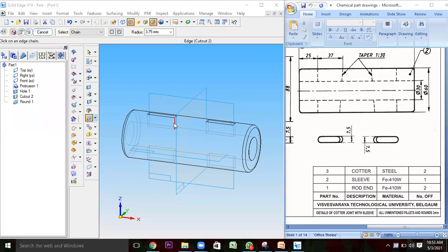I'm going to select this line and this line, this line and this line, and I've pressed the Control button on the keyboard, and I'm selecting all these lines over here, here, and in this portion, this portion, this portion, this portion, and this one, and this one, and this one. And I've changed it to edge and corner, and I'm going to select round and accept the format, and after that I'm going to click on this preview, and after that I'll be finishing it.